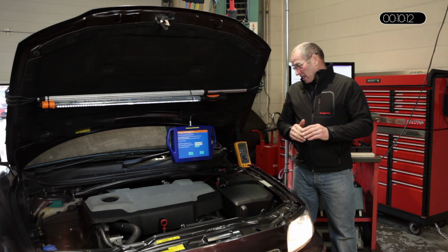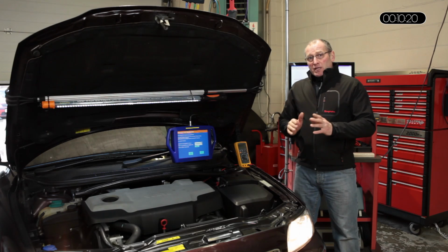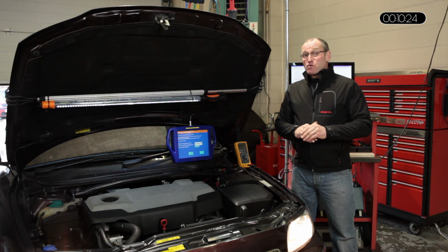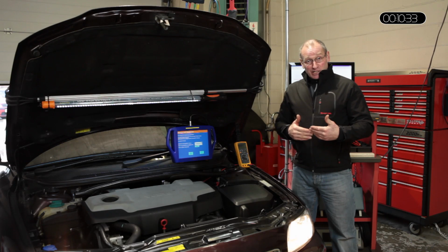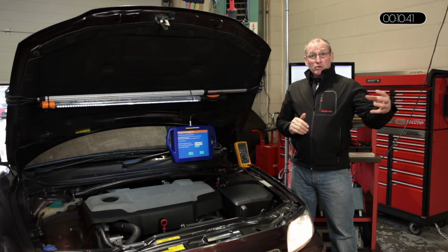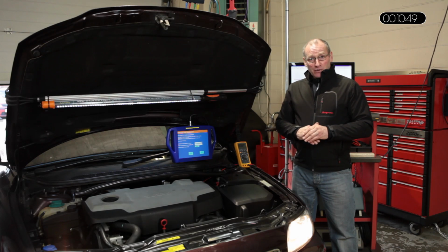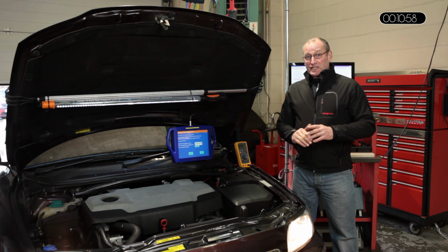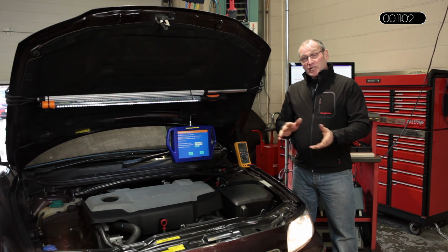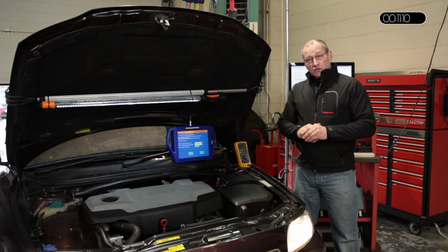So we drove the vehicle, we noted 22 grams of soot, and we had around 300-350 HPA pressure. The pressure differential sensor is a fully floating sensor. By that it has no reference to atmosphere. It measures pressure differential on the forward face, that's the engine side of the sensor where the exhaust gases are presented, and at the rear of the sensor, which is the exit route from the DPF. So it's measuring incoming pressure and exit pressure differential. And where that differential becomes excessive, it will then set a default, reducing fueling, reducing turbo boost, basically just reducing power. And until that's rectified, the vehicle will not perform correctly at all, nor, if it's excessive, will it allow manual regeneration. In which case, as was our condition, you then have to take the DPF off and replace it or clean it. So much for the serial data.